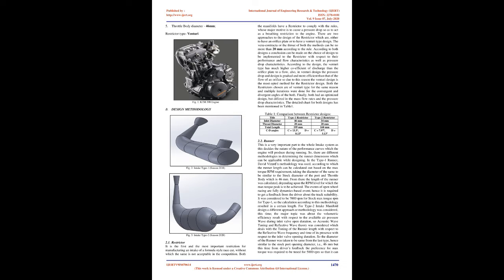1. 20 mm restrictor should be placed between the throttle body and the engine intake port. 2. Should be inside the roll envelope of the car. 3. No more than 710 cubic centimeters engine can be used. 4. The engine should be a 4-stroke engine. Engine selection, internal combustion engine.